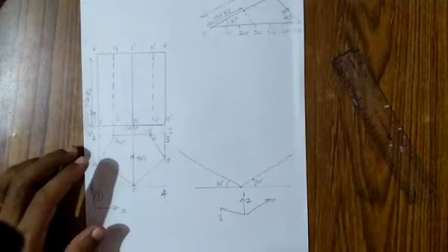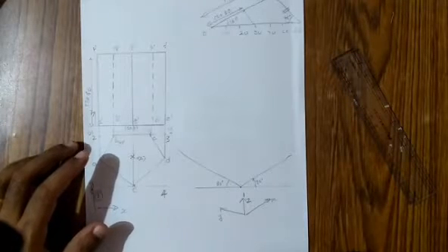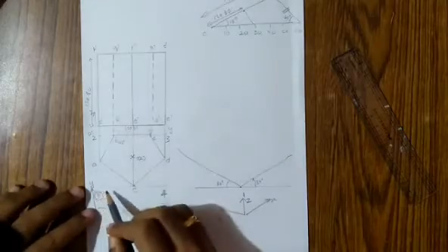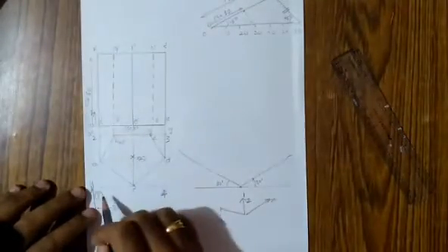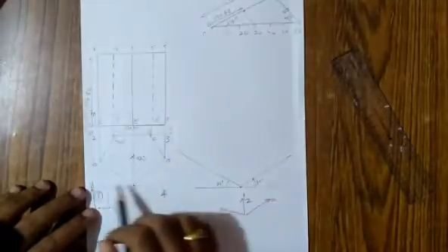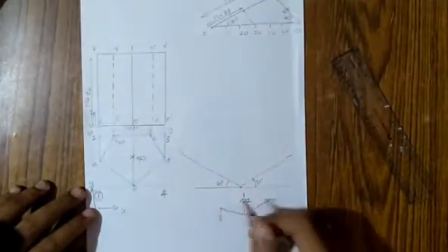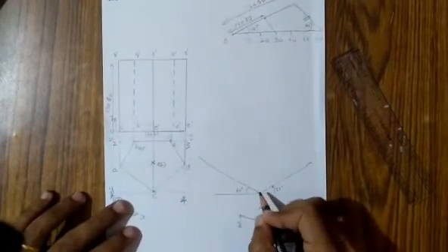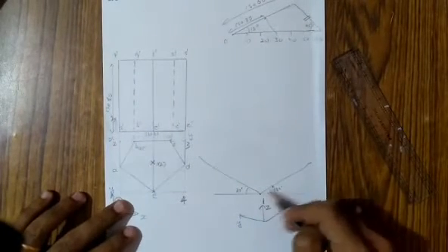So you are going to draw this pentagonal prism, and for the ease of doing that, we are enclosing it in a box. So this is the box having the base corners 1, 2, 3, 4. So that will appear as a lamina, a rectangular lamina. So we have drawn 1 first. From next we are going to move in the X direction.